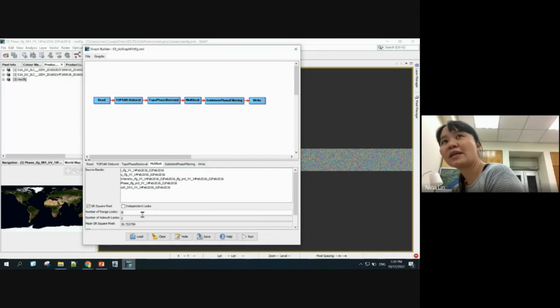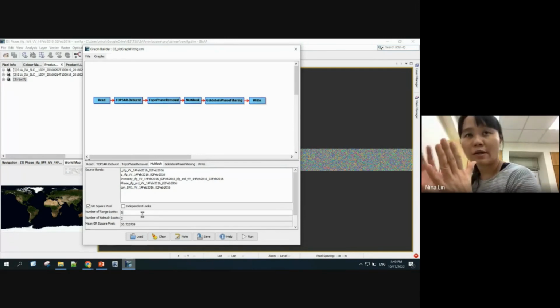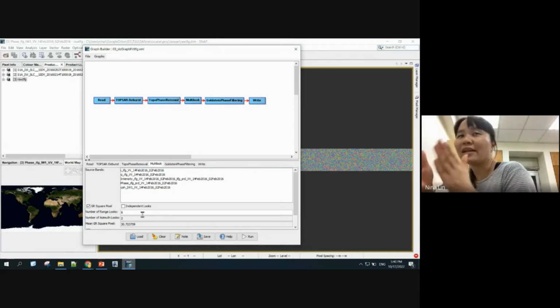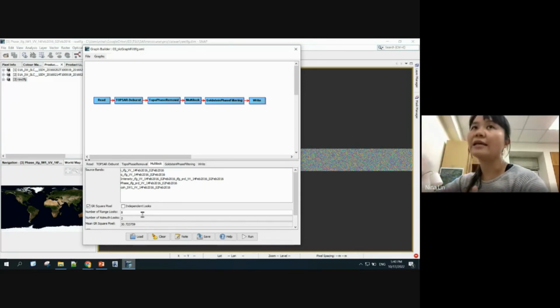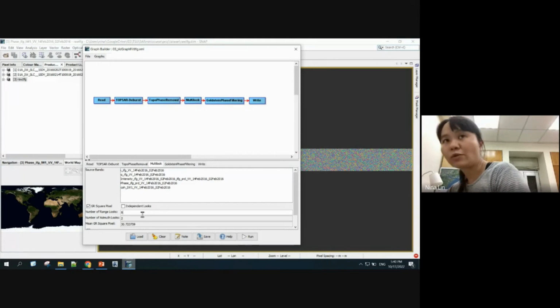Then you can immediately understand, because originally in the SLC, the original radar SAR image, the range resolution has a smaller number. It's actually about 4.5 meters in the range direction. And in the azimuth, or y direction, the corresponding ground resolution is somewhere around 14 to 15.